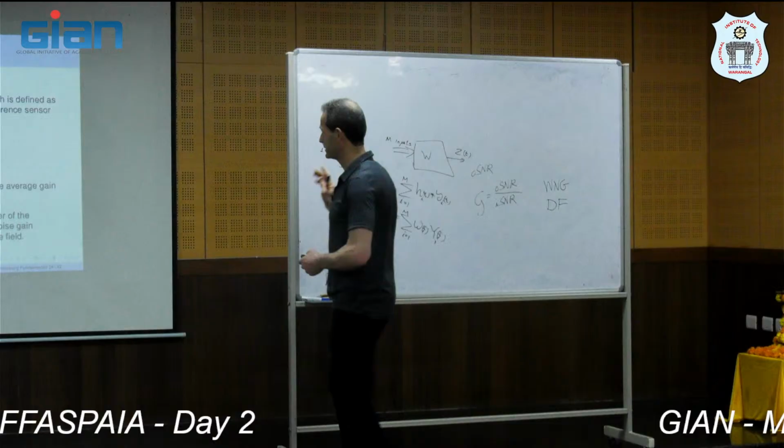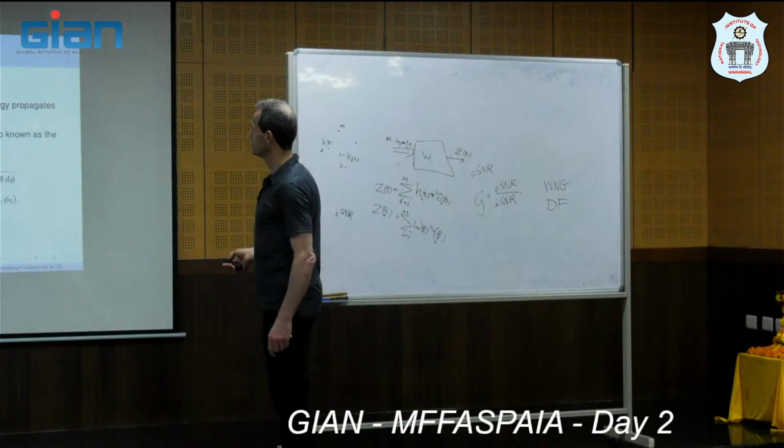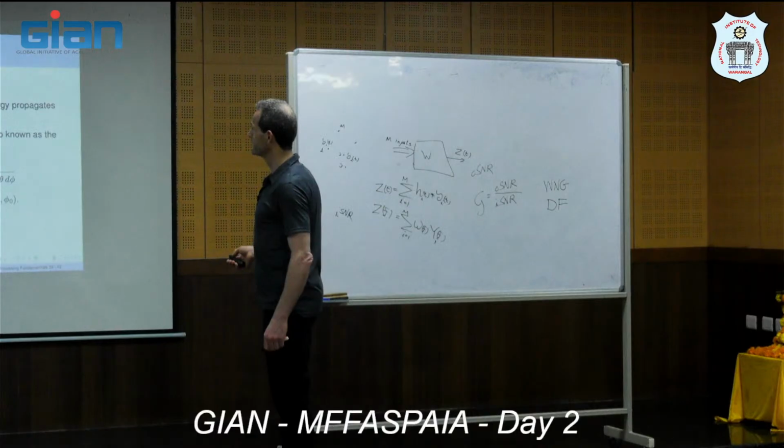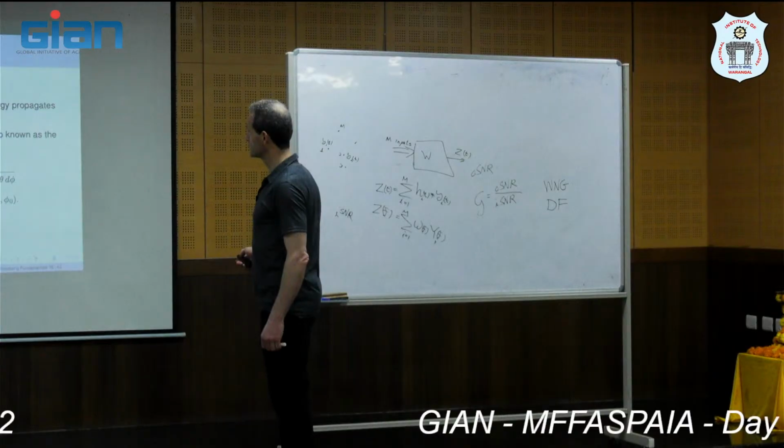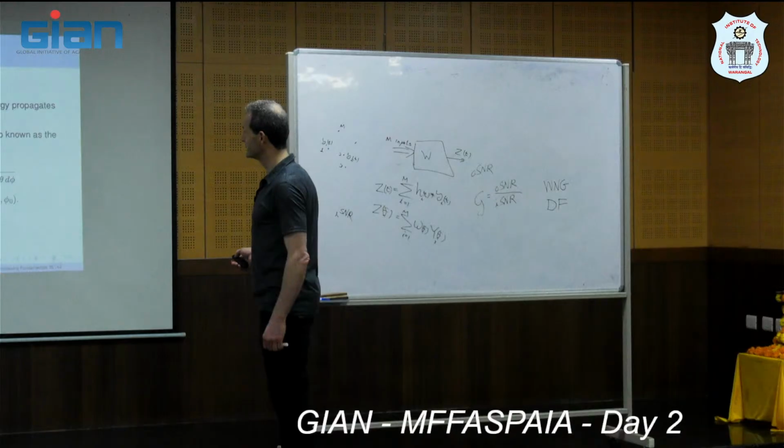And generally, if we have this array gain, we obtain it from the directivity pattern. The directivity pattern for a certain direction, the direction of the desired source: the magnitude squared of the directivity pattern in the desired source direction is the gain of the output desired signal.